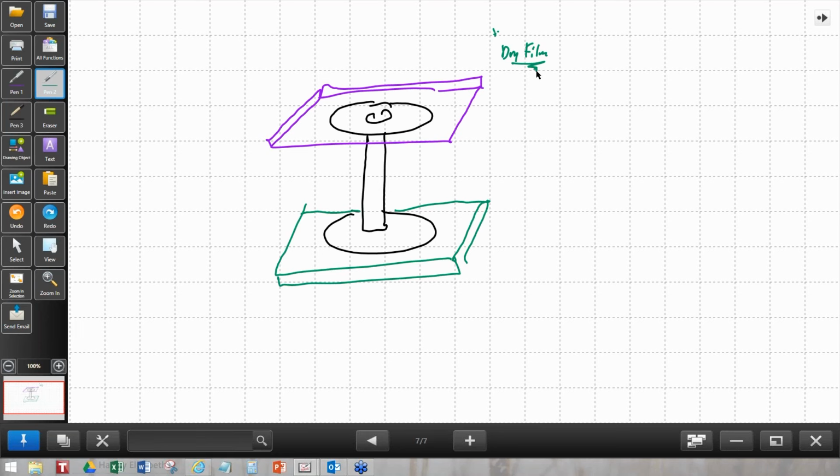If the hole is sealed, then there is air trapped in it. If this was sealed and made at the time that the board was ultra clean in a fabrication process, the inside of that barrel may be sealed, but it can be very clean. And many, many people rely on that. Some people don't want to rely on that, so they want to clean it. All right, but if you have it tented both sides with dry film, then oftentimes you won't get moisture trapped inside because the dry film blocks it from getting in. All right? So this is oftentimes done. Otherwise, how do you keep it out?